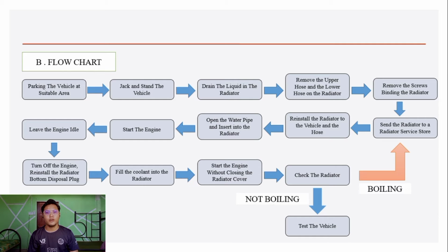After that, we turn off the engine and reinstall the radiator bottom disposal plug. Next, we fill the coolant into the radiator. After that, we start the engine without closing the radiator cover. And lastly, we check the radiator.